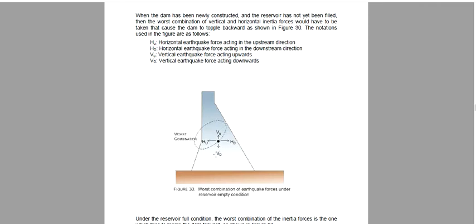So this is the worst combination of vertical and horizontal inertia forces while the dam has been newly constructed and the reservoir has not yet been filled.